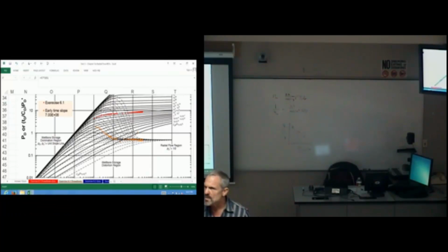I would like you to be able to get perm. Now in this problem we don't have wellbore storage, but if we had wellbore storage you should have been able to get T sub D over C sub D and actually skin. I want you to be able to work that way by being able to get a type curve match and get permeability and skin as if there was no specialized plot whatsoever. Because in some applications we don't have specialized plots. The type curve is all we got.